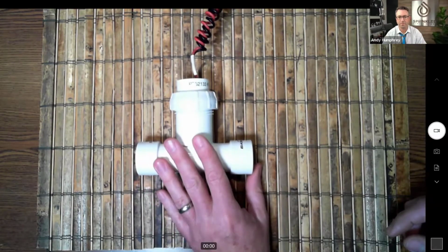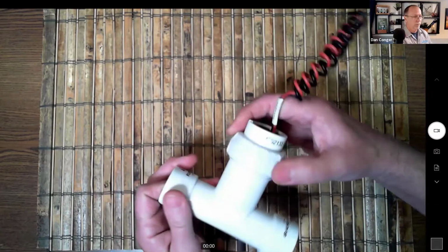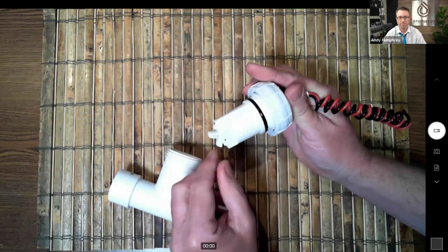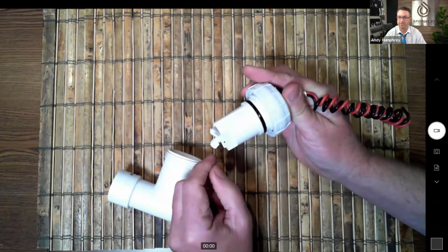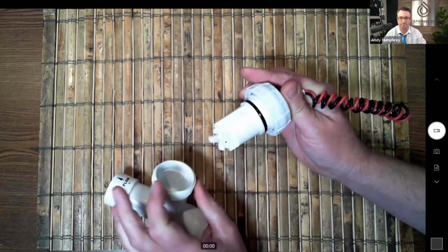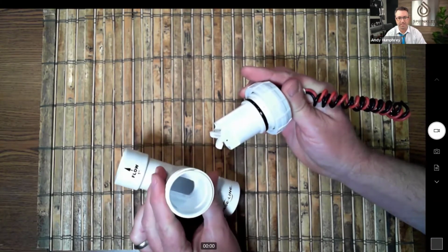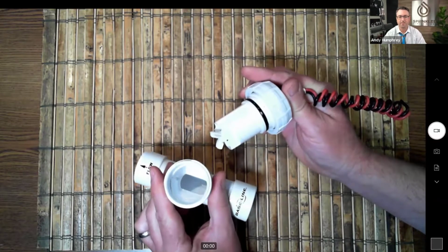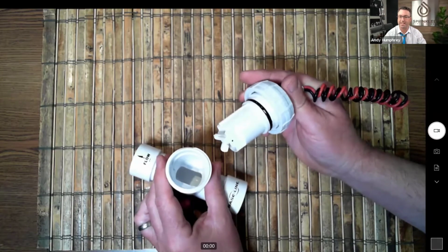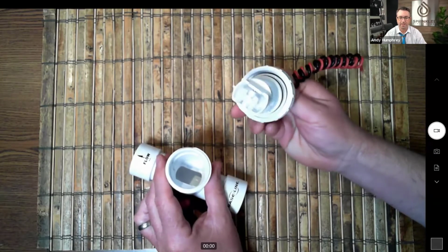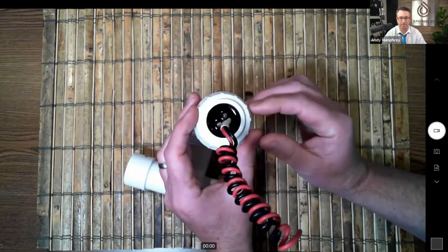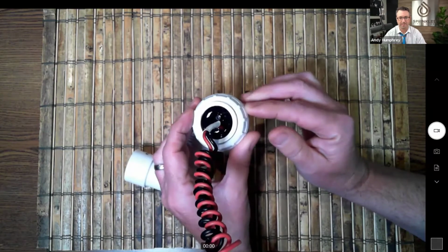Can you pull that out one more time, Dan? Sure. The insert, the paddle wheel. There's just something I wanted to mention, that occasionally it's nice, maybe during blowout or such, to examine the paddle wheel, make sure it's clean and there's nothing obstructing it. I was on a site a number of years ago where they were complaining that there was no flow, right? That was the support question. We're not getting any flow readings. And the LED lights weren't flashing on the top, and there are some steps you can go through to troubleshoot it, but come to find out it had been removed.